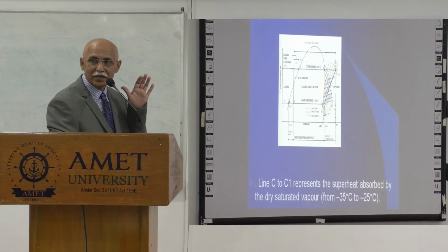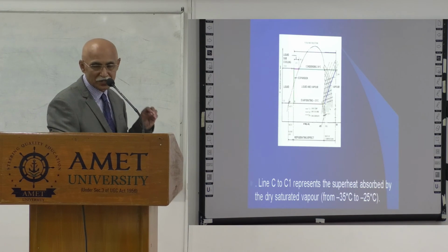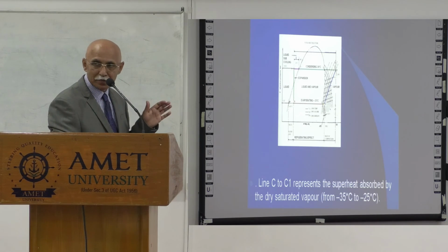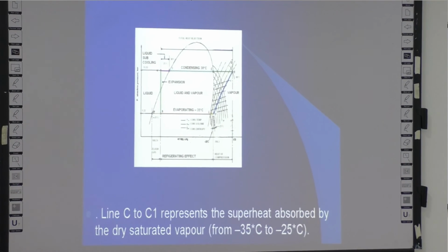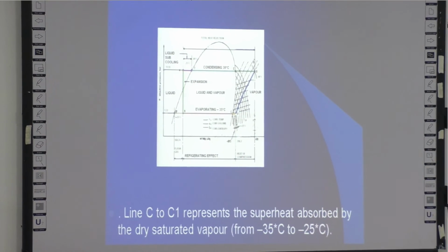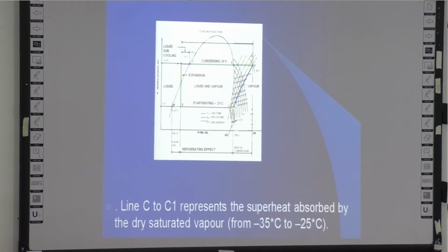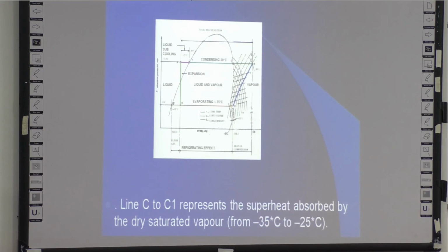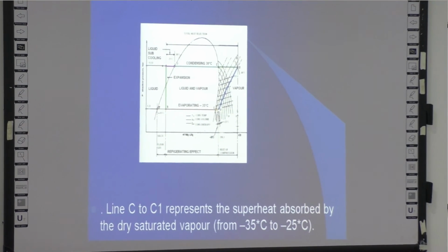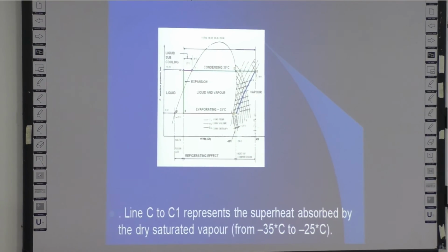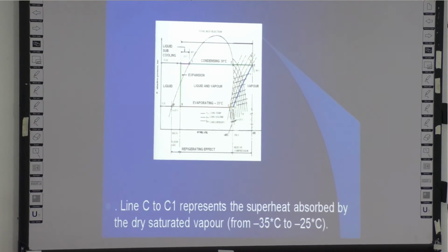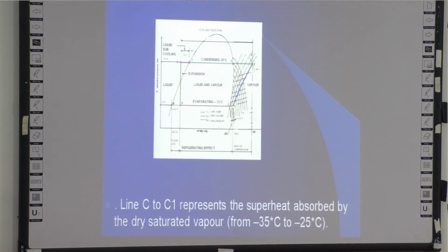Gas entering the compressor is at its least energy levels and lowest pressure. When it exits the compressor, it is at the highest pressure and highest energy levels. In the condenser, the energy levels keep dropping, and the pressure remains constant. Then in the expansion valve, it expands into a lower pressure with energy levels fairly constant. I think this should be easy enough for you to follow to draw a pH diagram in its simplest state.